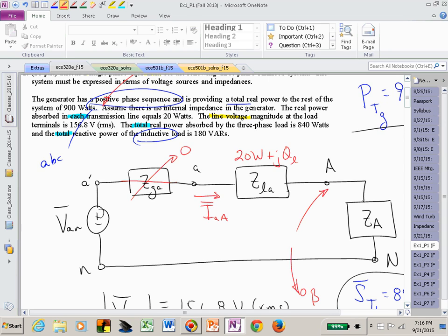It depends on what you're doing, but if you keep track of the phase quantities, meaning the phase voltage would be V sub AN and the line voltage, then that V I times cosine theta would be your power in that particular generator phase.